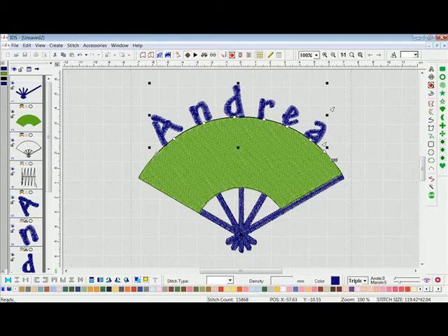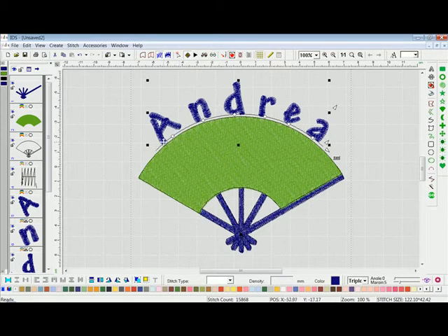This time I will set them here, left click to select, and here, left click to select. Then I'll place my cursor over that baseline, left click when it's blue, and now you can see that my baseline is now 2 millimeters above what I had selected.